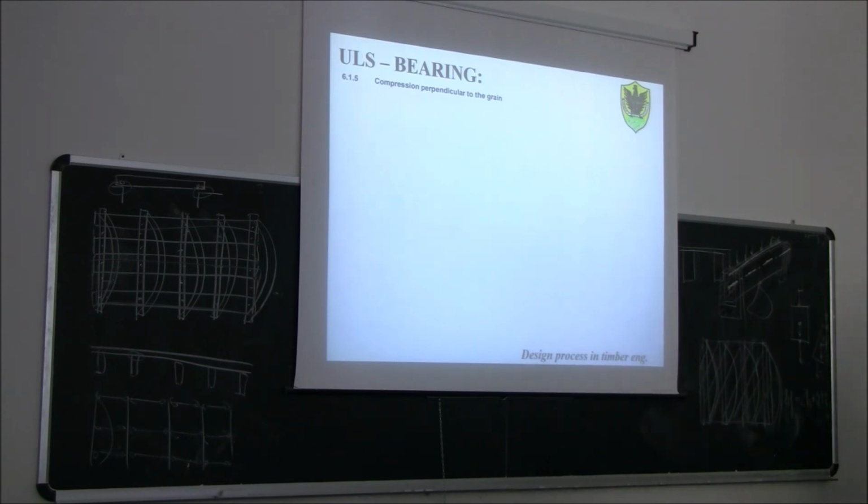So, first of all, those stresses here, usually, they are much less compared to the primary stress. That's why we call it secondary stress, because in terms of magnitude they are much less than the one parallel to the beam axis.